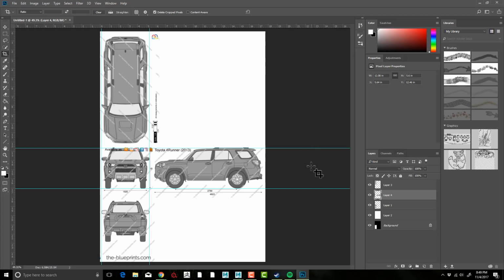And normally I'll have a bunch of other photo references set up. So this is a good opportunity to fill that space with your other photo references. So if you have a 3/4 view or something like that, that way you have them in Maya to see them. So you don't have to, especially if you're working on only one monitor, minimize Maya to look at your reference and then bring Maya back open. So you'll have them right there in Maya. So this is looking pretty good. So I'm going to go ahead and save this out.